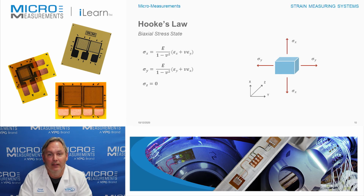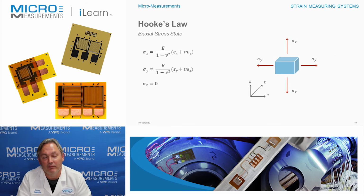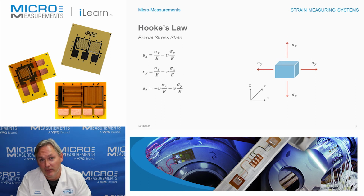So what does that mean to us? Well, what that means is that we've got to install at least two gauges on our structure, one perpendicular to the other, or we put on what's known as a two-element T-rosette, which has two grids that are perpendicular to each other. We take two separate measurements, and from the two separate measurements combined with the material properties, we can calculate the stress in the X and stress in the Y direction.